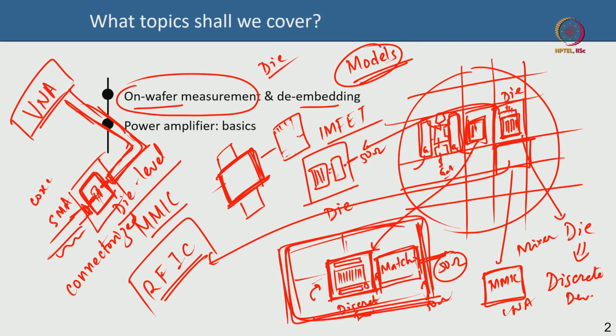You can develop and build models, verify, validate them, and once you do that, it's easy now for you to actually get rid of these pads, CPW pads. You can actually make devices that are for real world application. You can dice them, package them, match or unmatch. You can build models and you can predict their behavior. So that's very important. On-wafer and not on-wafer. Okay, when I say not on-wafer, I mean connectorized measurement. Connectorized measurement and on-wafer measurements, they have their own uses and their benefits. So we need to be aware of both of them.